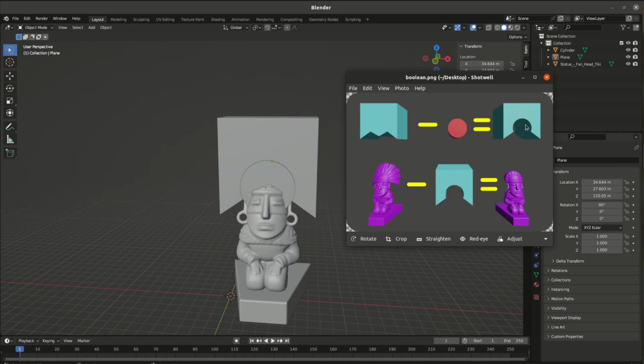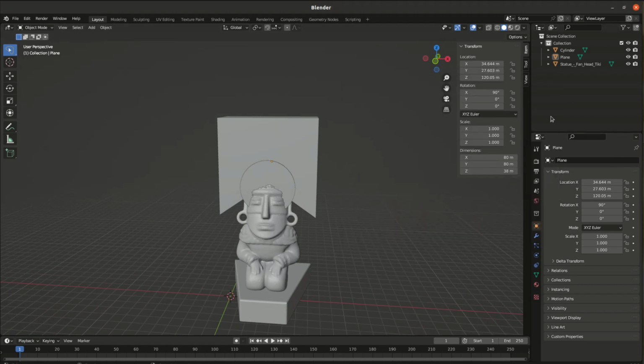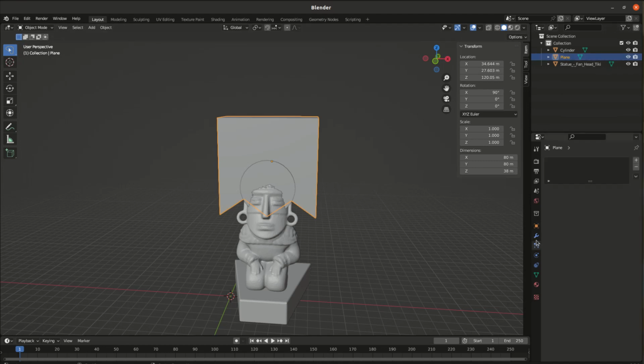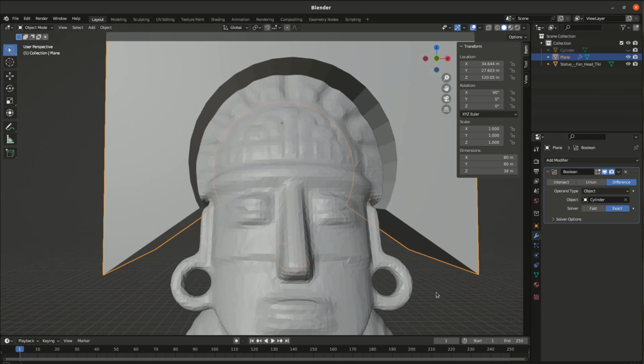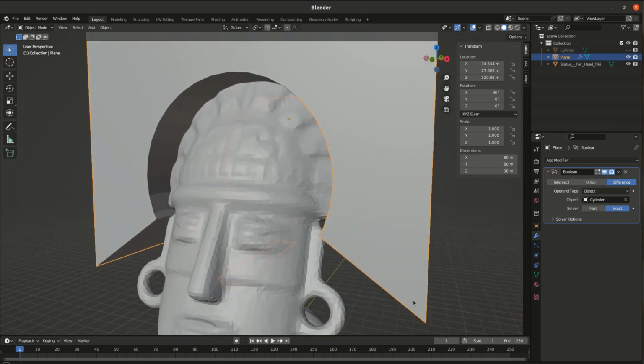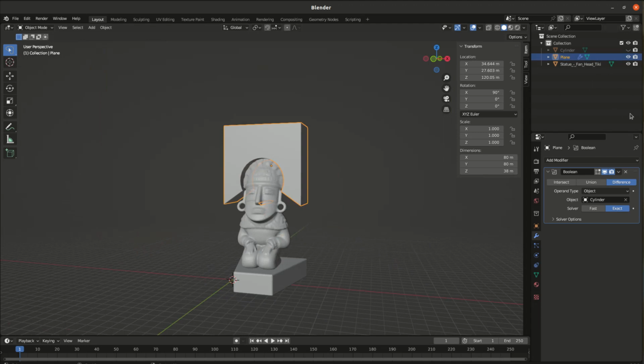Use the block minus the cylinder with the Boolean difference and get this object. How can we do it? We can just select the plane here, and we're going to go to add modifier. We go to Boolean and then select object. We can select the cylinder. The method is different, so we can see the difference between them. And now if you turn off the cylinder, you're going to see the state is there with the part already cut out. So we have the first part here.